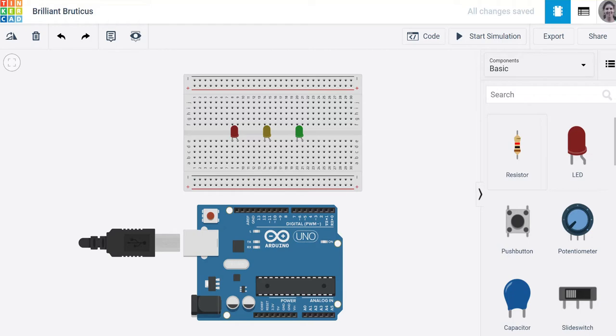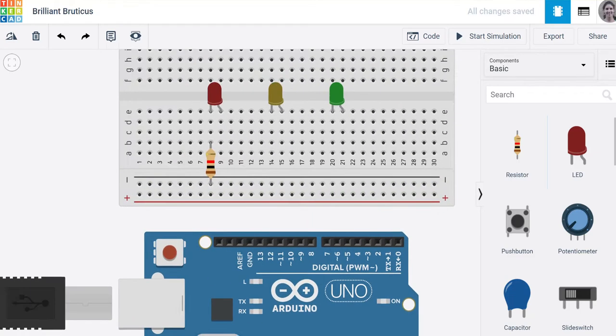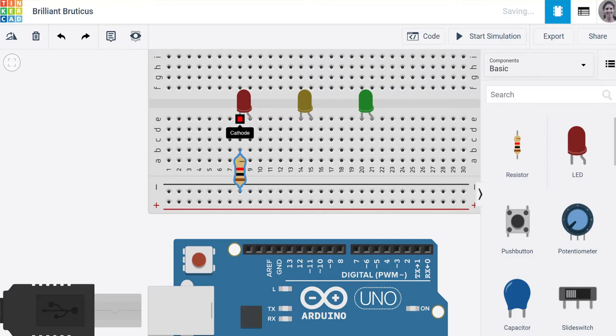What is great is that we can add the resistor either on the minus or the plus side. We will use the minus side because it's a bit easier there. So grab a resistor and, okay, I will show you. Let me just show you up. When you add the resistor, it should be in the same column as your cathode and in the same row as the minus. Okay, so terminal 1 in the minus row and terminal 2 anywhere you want, but it will be in the B, next to the cathode of your LED.